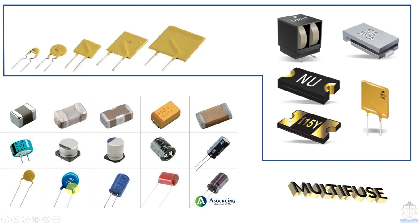So the question is, how will you come to know whether this is a multifuse or a capacitor? Some value of capacitance will be written over here. Here it is written 102 15 kV, etc. But on this multifuse you won't find any sort of data, meaning you will not find voltage and all that. You will find only the temperature and some other values that are not relevant to capacitance. So by seeing this you can identify. Another thing is that these multifuses are very thin, whereas these are a little bit thicker. So by these two ways you can identify which are the multifuses and which are the capacitors.